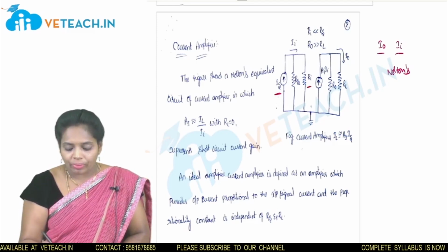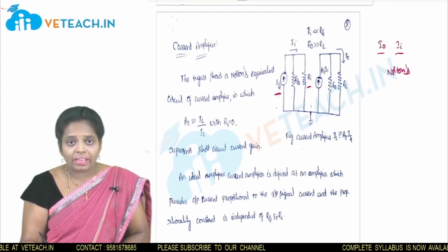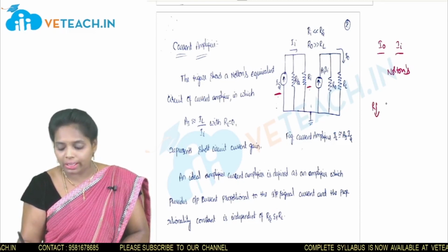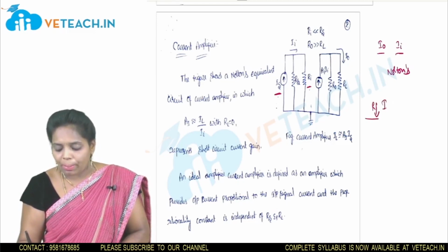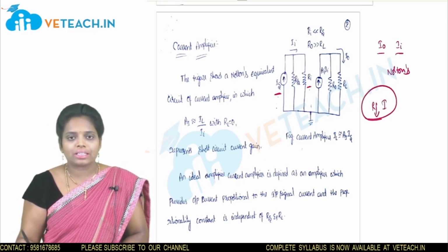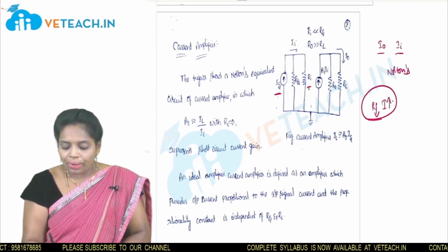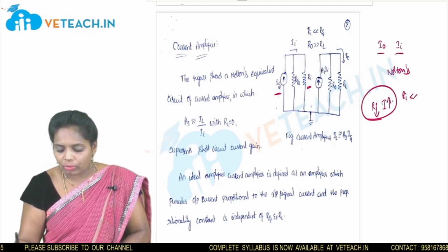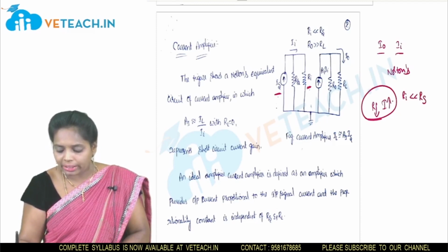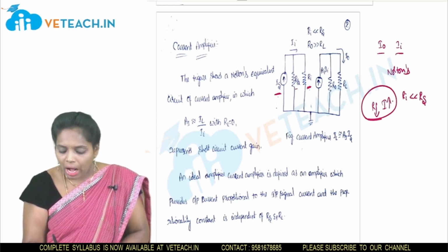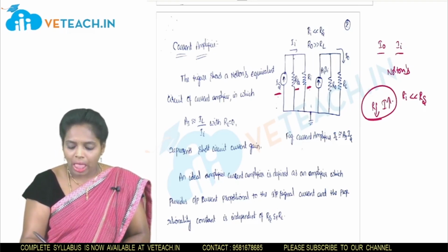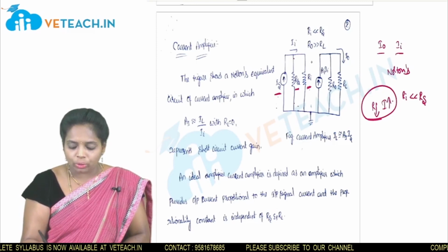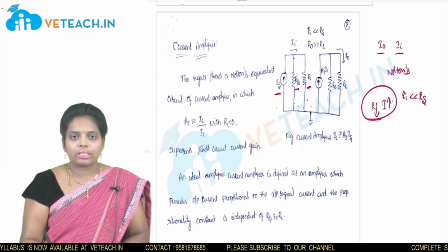So when will the total current exist? We know that whenever the resistance value is very small, the amount of current passing through that resistance will be higher. So by using that, the value of Ri must be far less than this Rs, which means the value of Rs should be very high. Whenever the Rs value is very high, it acts as an open circuit. Then the total current passes through the transistor only.